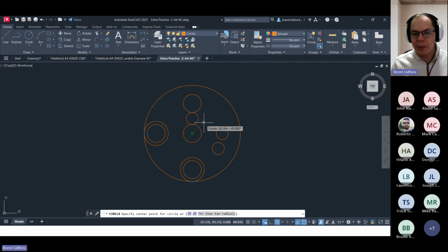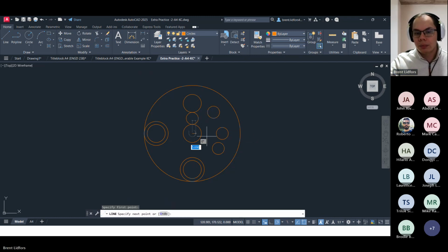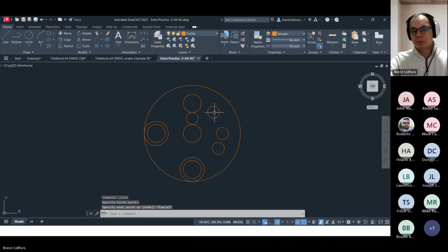And then again, I can type in the radial distance, exactly 50, hit enter, put in my radius, hit enter, and now this is more exact. Okay, so it's not showing any hanging decimals because those decimal places don't exist. So it's just a precision thing that you need to watch out for.